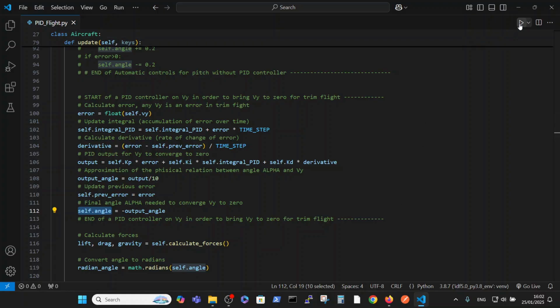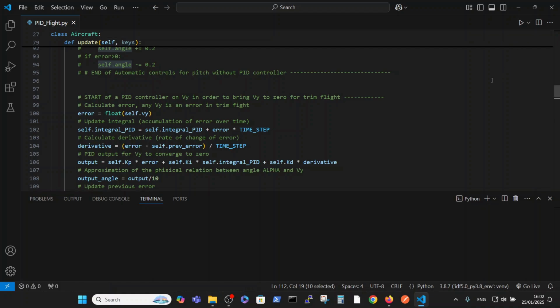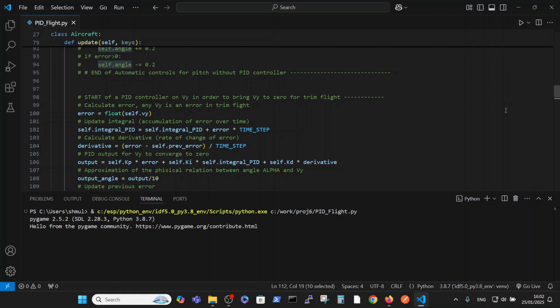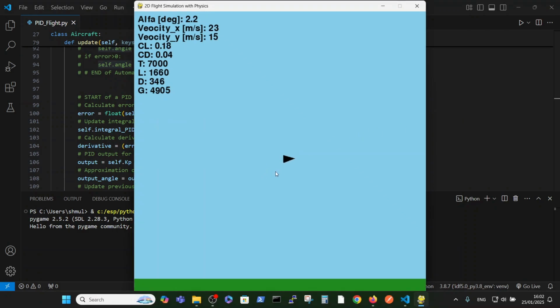In order to summarize, I will run it once again. We have the basic airplane model with the PID controller, which is implemented with only a few lines of code without using any kind of special libraries. And you can see that this controller is working pretty good relative to our hand managed controller or the Bing Bang, the simplest controller that was implemented.